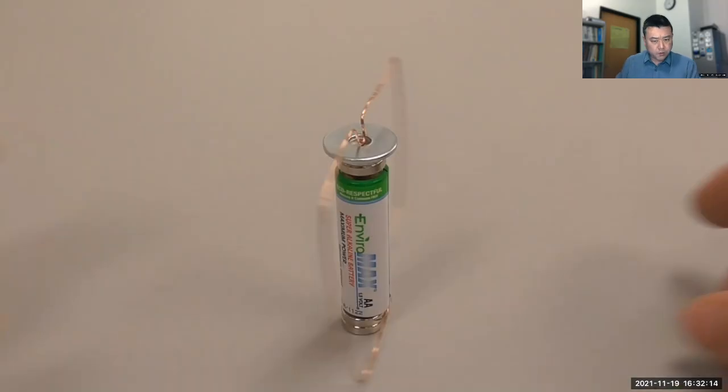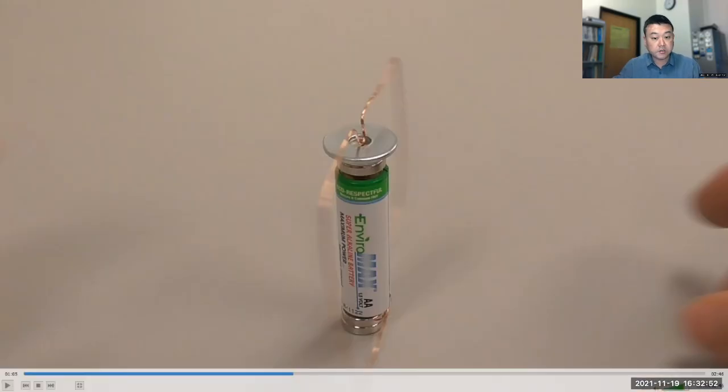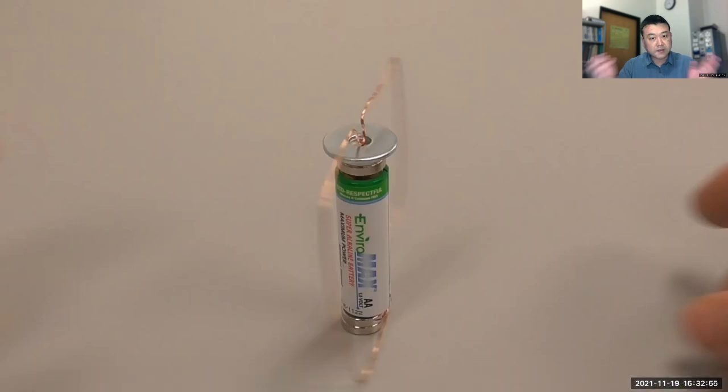It's called a homopolar motor because that's the design of this arrangement that's different from the other motor you have seen. In the other motor, we had to deliberately make the electrical connection asymmetric so that basically the pole of the electromagnet in the coil of loop switches. So the direction of the magnetic pole that's produced by current is changing as it turns one full turn. In this arrangement, it doesn't change. The direction of current stays constant throughout the entire revolution. That's why it's called a homopolar motor.